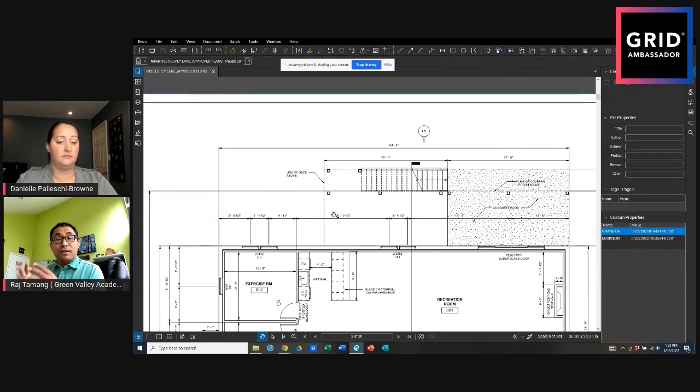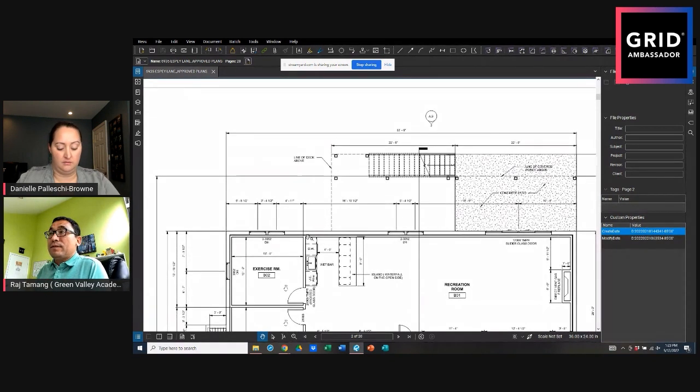So think about all the information you have to put in the drawing so that they can understand it clearly. That's the perspective. You understand it as a designer or architect because you designed it, but you have to think about whether the contractor who is actually building it can understand it. That's how I see it when I prepare the plan. All the dimension information should be there.